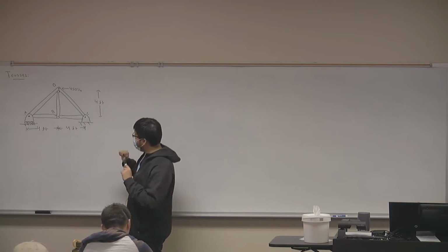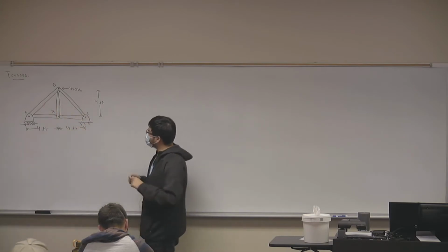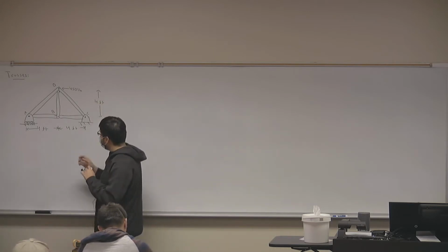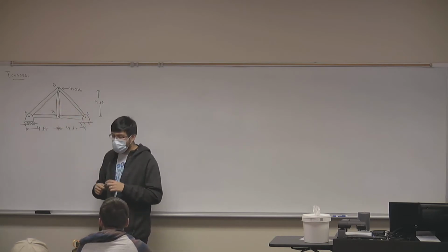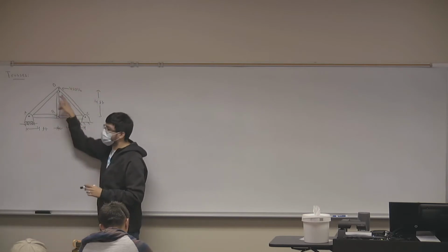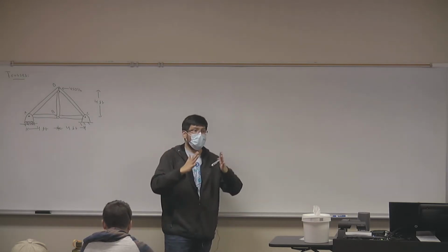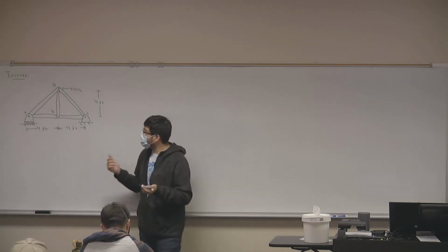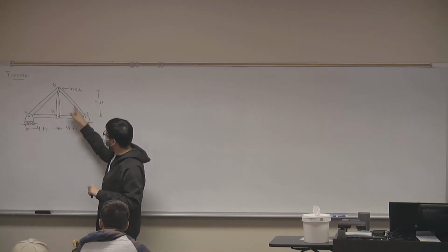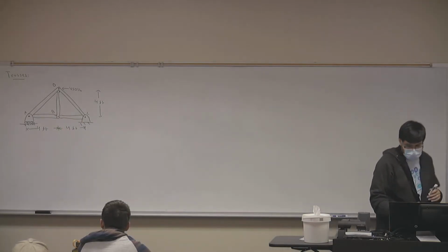So what I want now is to find the forces acting on each of these trusses. Now, these trusses are rigid bodies. If I apply a force of 450 pounds, just think conceptually, what forces can these elements experience? Well, because they are rigid bodies, and notice that this force will either push or pull some of them based on these hinges, the only forces that they will experience are going to be either tension or compression. Is that correct? So we're not really going to consider any shear force, any bending forces, but we will try to find the tension and the compression that each truss experiences.